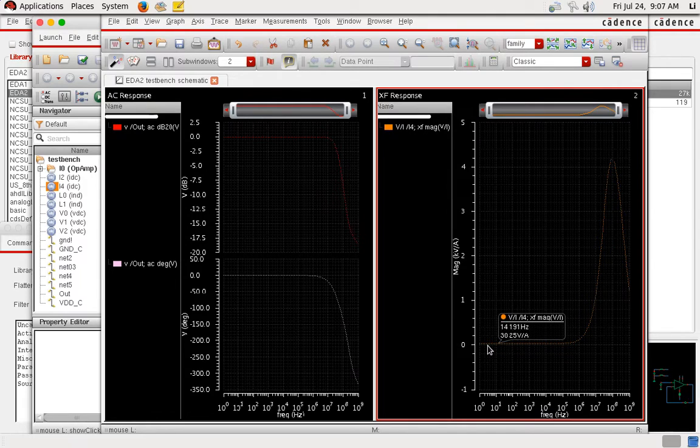And this plot also is reasonable. If we check out low frequency, the resistance is about 30 volts per amp, which means 30 ohm, okay? And if you do a hand calculation, you'll find out the value should be pretty close, all right? And this should be a good representation of the output resistance you are looking at. All right, do we have any question?